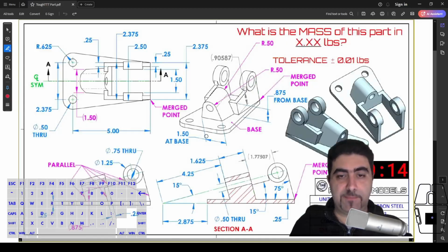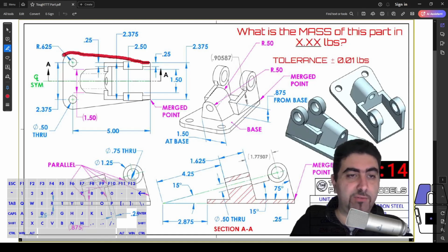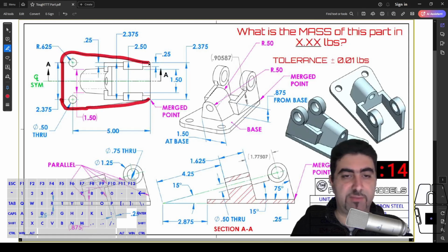Okay, well, we will start with this floor, right? And you've got this edge here, which is 2 3/4, 2 3/8. Okay. Then you flare out, you do this arc, which is a 0.625 arc, and then you go here, another straight line, and then you have this piece closing everything up. So this is pretty straightforward to design.